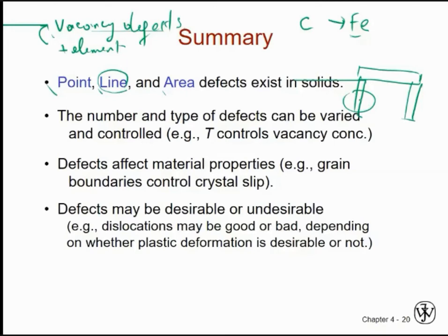If these pillars deform, it's catastrophic, the building will collapse. In this case, you don't want your building to deform. For another case, you have a phone, let's say an iPhone. You would not like your phone to deform and not return to its previous shape when you carry it in your back pocket. So in this case, you don't want it to deform. So how can you do this? By getting rid of those dislocation lines. The fewer dislocation lines, the more strength.